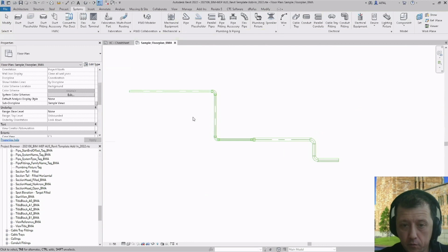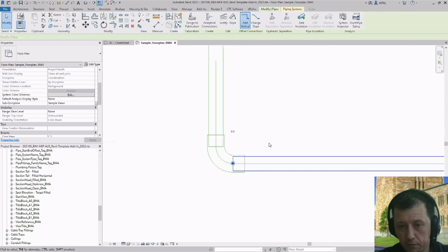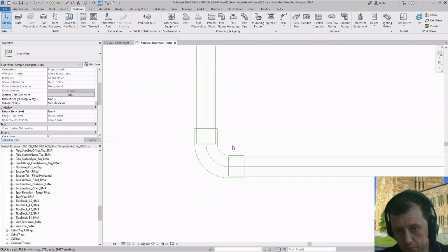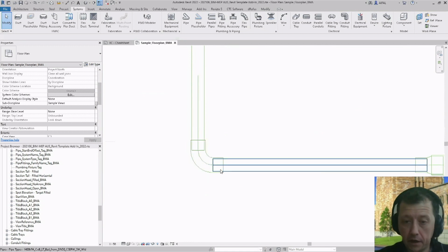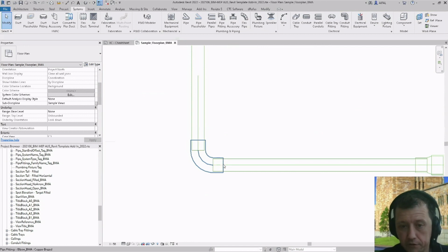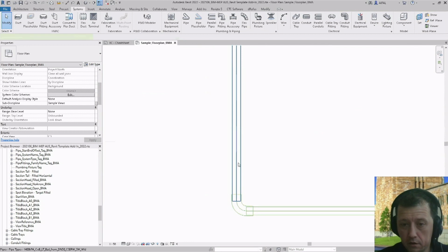Another thing that I wanted to mention here is the position of the connectors. Some people think that this is a bit weird how that looks. Our connectors sit inside of the fitting, because of some feedback that we got from the industry that many pipe fittings have the connector sitting outside of the fitting, which at the end means that you have the wrong length of the pipe.